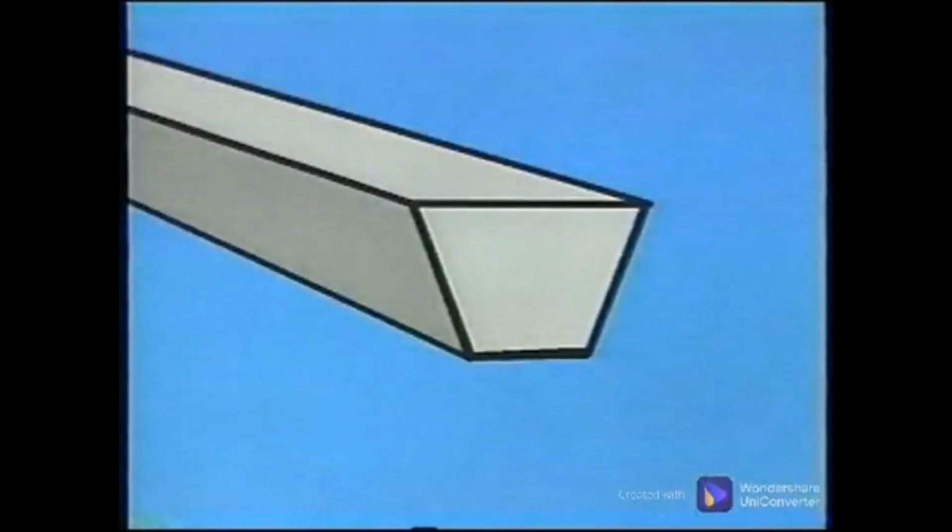The V-belt has straight sides, but as it goes around the sheave, the bottom half of the belt compresses, causing the sides of the belt to bulge and wedge tight against the groove walls. And while the bottom half of the belt compresses, the top half is in tension and stretches. The center part of the belt is the only part of the belt that does not change shape as it passes around the sheave. This part is reinforced with cords. The cords enable the belt to carry loads.